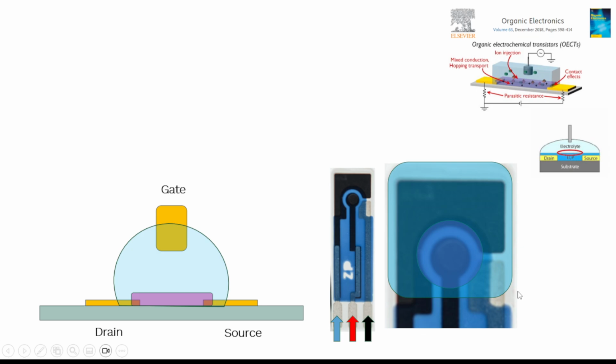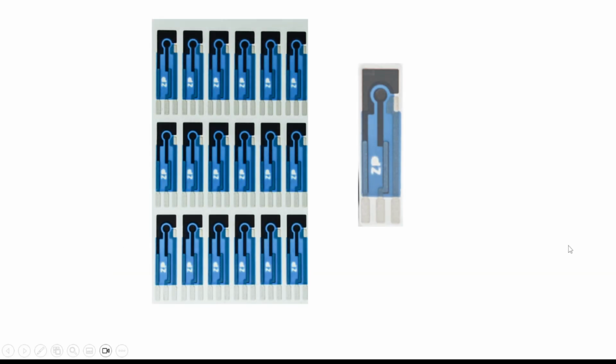organic electrochemical transistor, an OECT. So I hope that helps you, that yes, I think you can use screen printed electrodes as a foundation or a substrate for making OECTs. I actually think it's a really good idea, because your cost of materials and your ability to actually make and test materials is much, much easier.